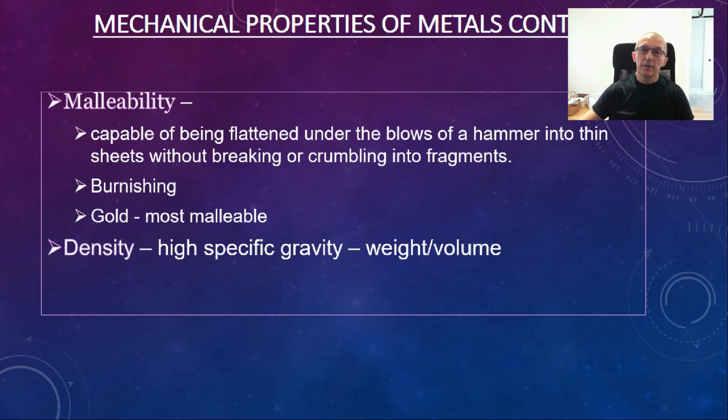And this can be calculated by taking the specific gravity of wax and the specific gravity of the metal, and we can get the weight or volume of that specific material. If we wax a crown and we multiply the specific gravity of the metal, measured in the same grams or pennyweights, then we get the weight and volume.